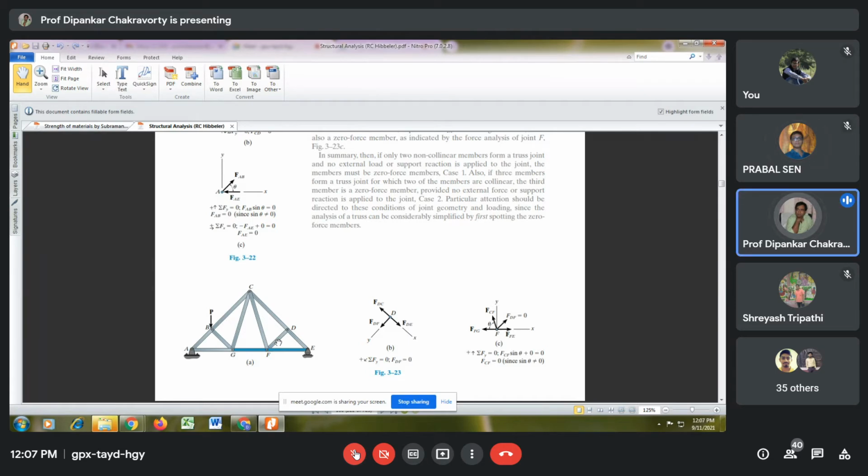Your answer is incorrect. I mean, your answer is correct but incomplete. Your logic is not correct. Why? Because CF is not at right angles with G. So CF should have a component along G, and the bar force along G will counteract that. Yes, sir. Your answer is correct, but your logic is wrong.